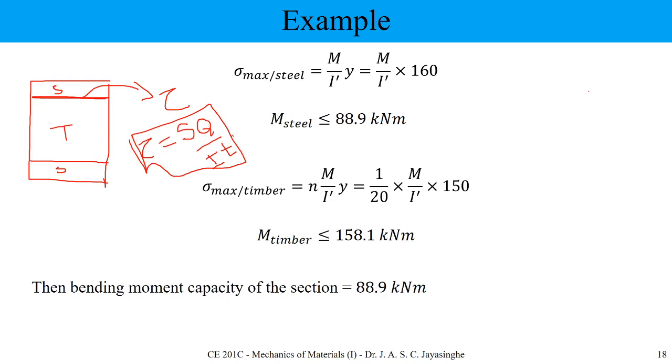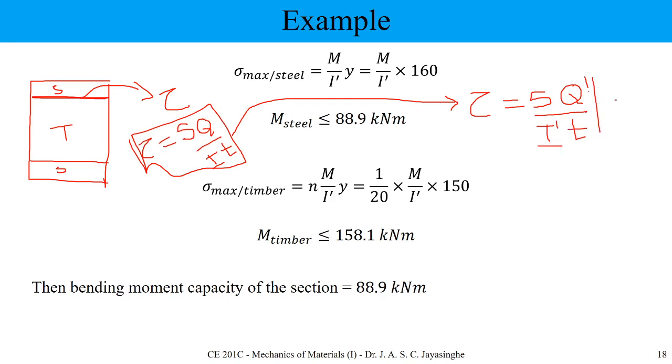So then you can prove the modified tau should come something like this. Of course, the shear force is not going to change. Q dash, you know now what dash means. I dash t actual. Okay, so you can prove this one. You can check it on the internet or anywhere else. You can prove it in a similar way.